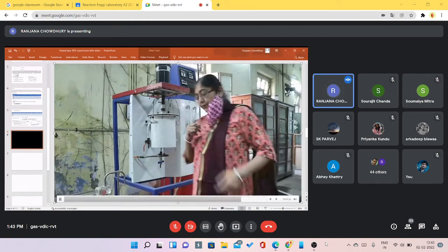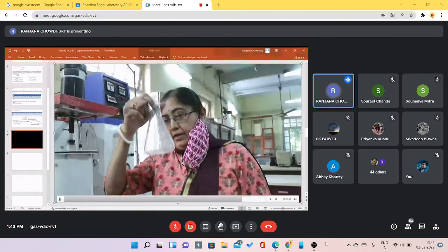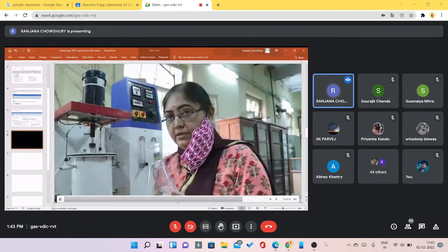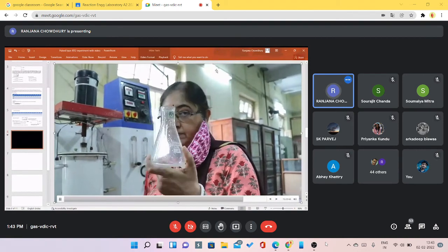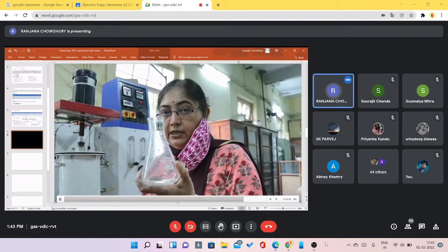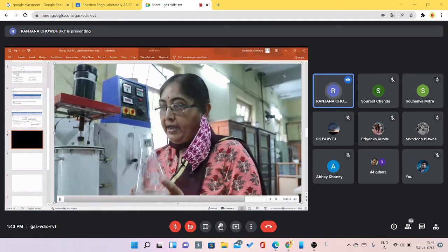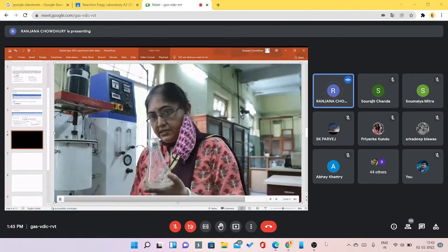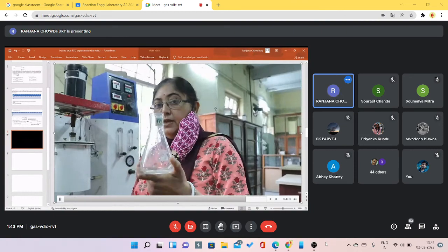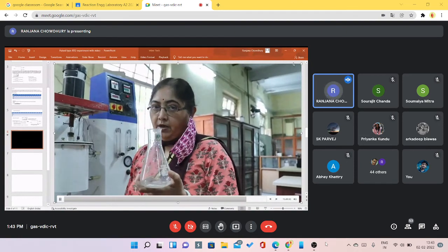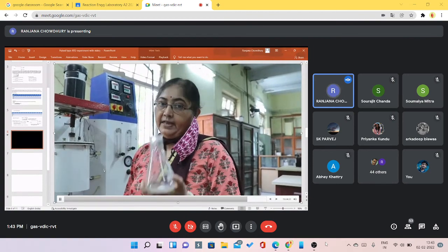That means if you titrate these samples, you can get the Ct values, the concentration of H2SO4 from here. From the values of Ct, you can directly draw the C curve by plotting Ct against t. And I have already told you how to determine Et and all the moments. By following those procedures, you can determine the values of Et as well as the mean time, the variance and the skewness.